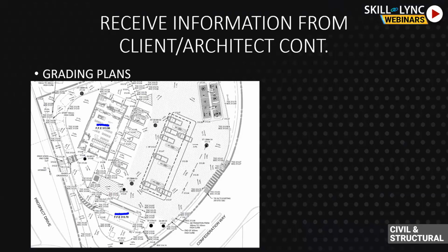But what if a client is also very new and you are also very new, and there is certain information, just to quote an example, a grading plan is required, it's a must when you're designing a building. And what if the client is new, and you are new and you miss putting this information into the structural drawings, you miss this information in the inputs? It's going to be a huge blunder when you go on site.